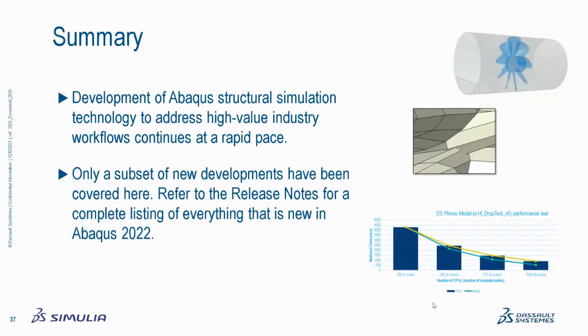Of course, scalability depends to a large degree on the size of the problem. You can't take a 1,000 element model and expect to scale it on 1,000 cores, but as the problem size scales up, the amount of the software that can run in parallel, particularly the solvers, becomes a larger proportion of the overall cost, and scalability is quite good.